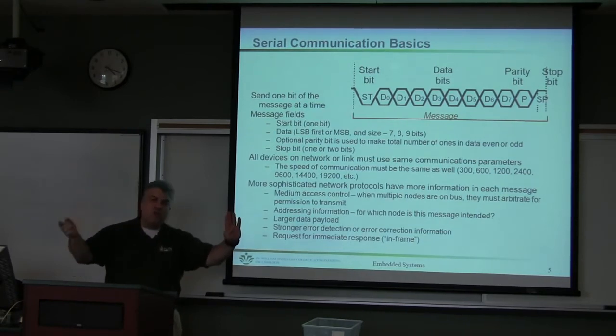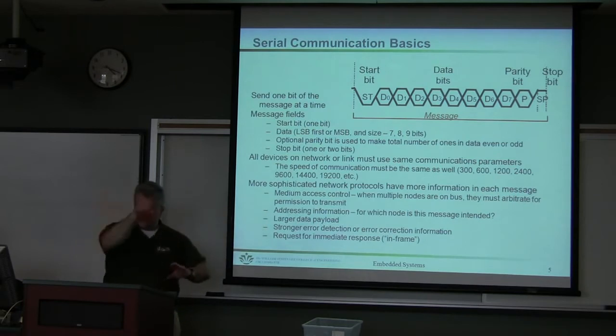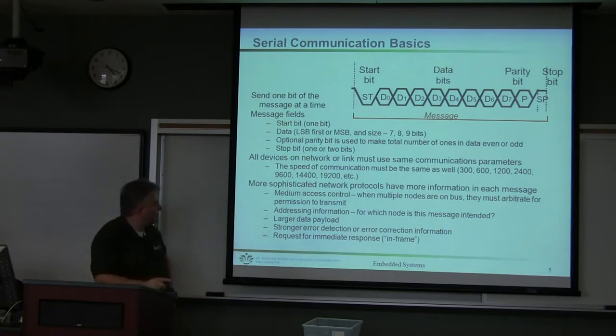And so if one is sending so much data at a certain speed, and this one is expecting it at the same speed, but its clock is really a little bit different, eventually the bit that it thinks it's sending over there is just ignored, because the receiver is not running fast enough to collect it. I'll show an example of this in a second.